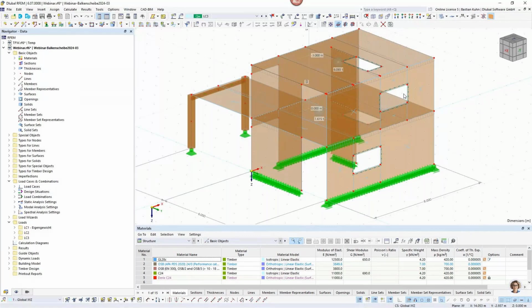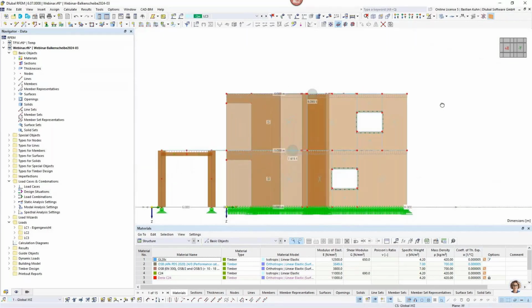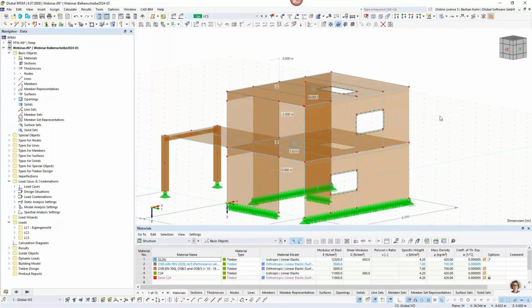And this is for a hand calculation. And what would you do when you calculate such a structure by hand? You would calculate your horizontal force, and then you would say, okay, this surface cell will bear this horizontal force, and this surface cell will bear this, and I need anchors here and here on this point, and I'm totally skipping the elements in here.